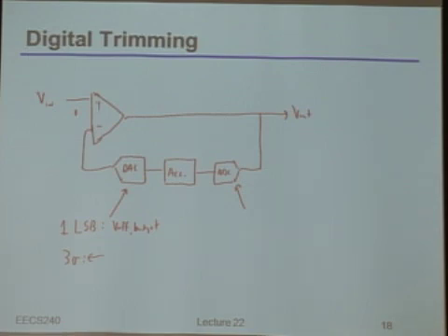So these ideas are actually quite powerful in that you can really apply them more generally to multiple stages of amplifiers, multiple stages of comparators, and so on and so forth. Because as long as you know how to cancel one of them, you can kind of bootstrap, right? You can use that good known thing to cancel the others and then repeat the same procedure. Make sense to everybody here? All right, so